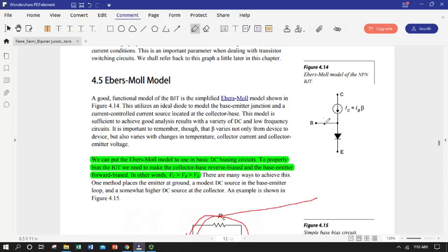Not surprisingly, we are representing the connection between the base and the emitter with a diode. We're representing the base emitter junction, the PN junction, with a diode, which is kind of where we started when we talked about the semiconductor roots of a BJT. So that's cool. We know how to work with a diode, right? It's basically like a little voltage source that pushes back in the direction we're trying to flow current. So this would be like a little 0.7 volt source with maybe some resistance.